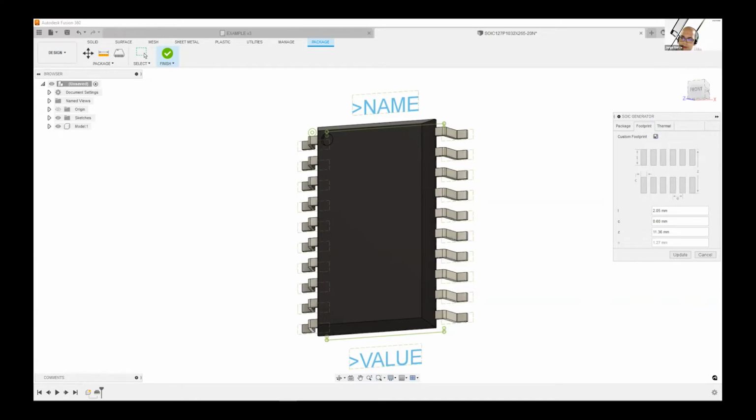If you're happy with the default, you just uncheck that and leave it alone. With thermals, some components have to dissipate large amounts of heat, and you'll notice that underneath the main component body, there's actually another pad. If the part you're working with has this, you check this box and define the dimensions of that pad.